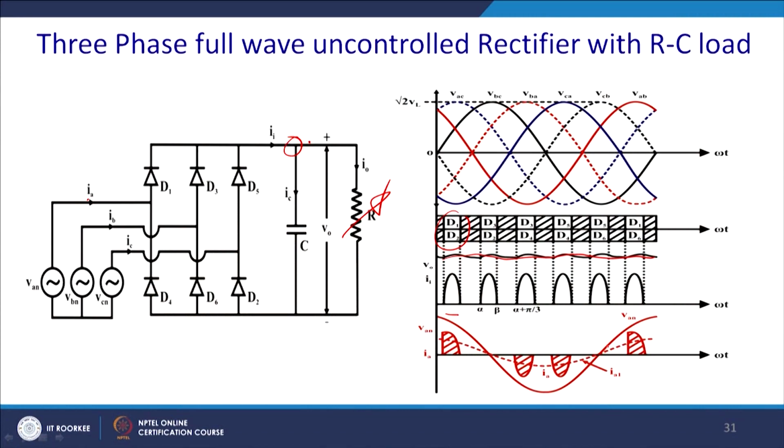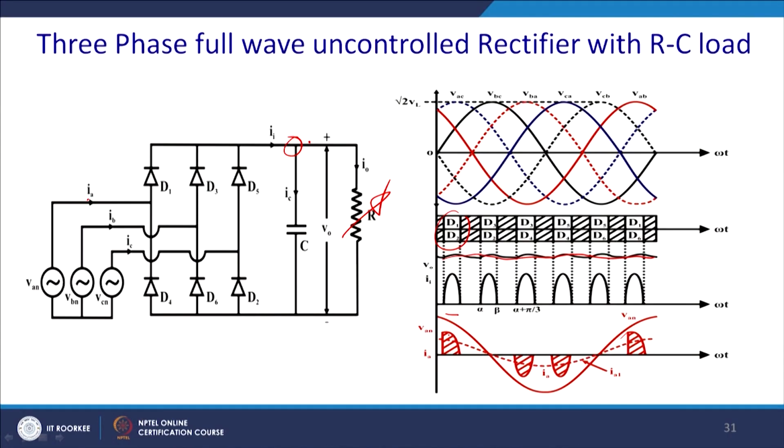Similarly, the current will have this kind of choppy profile, which is quite a disturbance and a unique problem to be solved. This is one of the issues with power quality, because you can see that it gives a choppy current while you have a sinusoidal voltage. So, this is the problem once you have an RC kind of load, and nowadays it is prevalent.